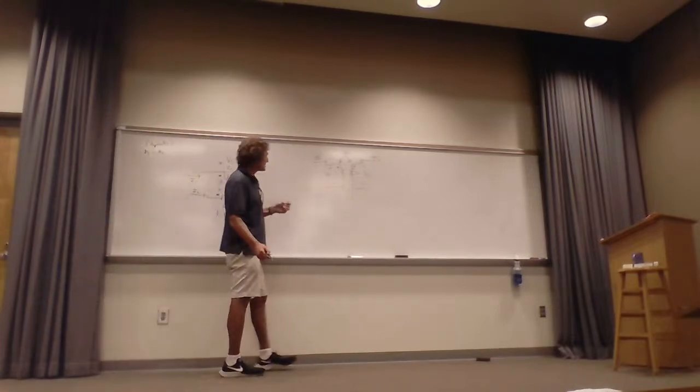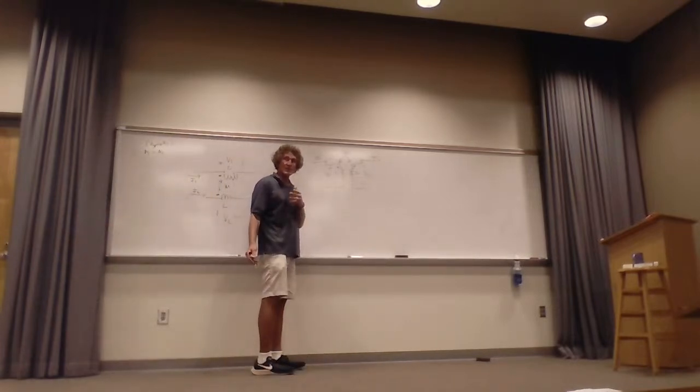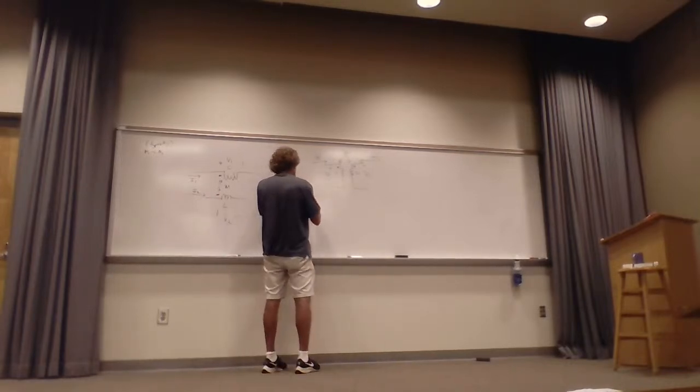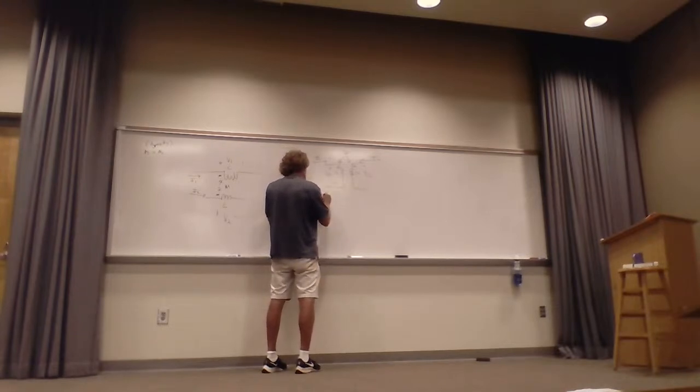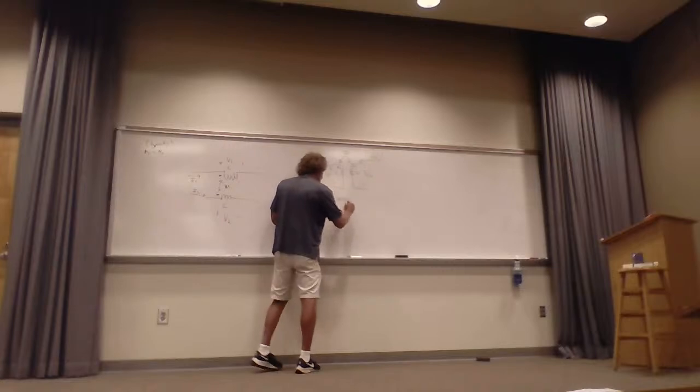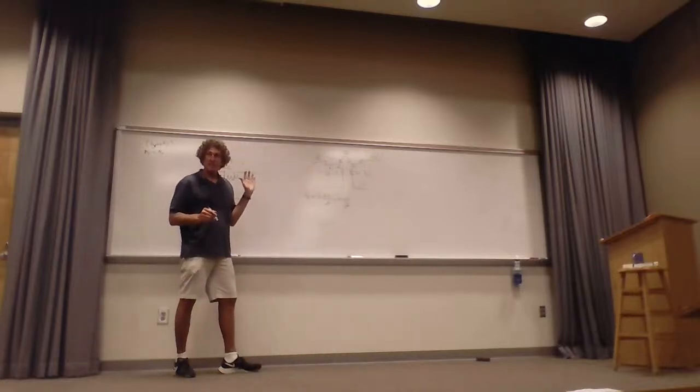All right, now if you remember the way it works, I'll go to the time domain and then the frequency. You don't need to write this. I'll tell you what to write. Just watch. When I look at V1, technically V1 is equal to L dI1/dt plus M times dI2/dt. Y'all remember that? That's in the time domain.